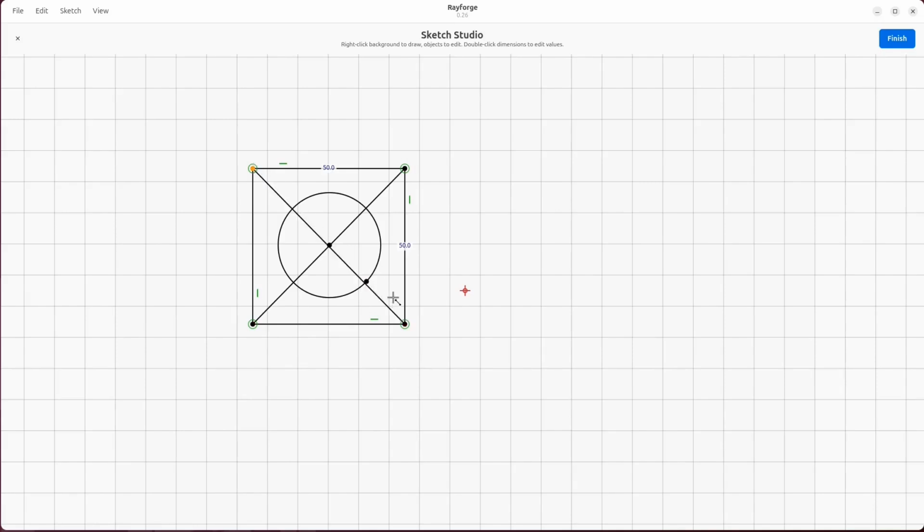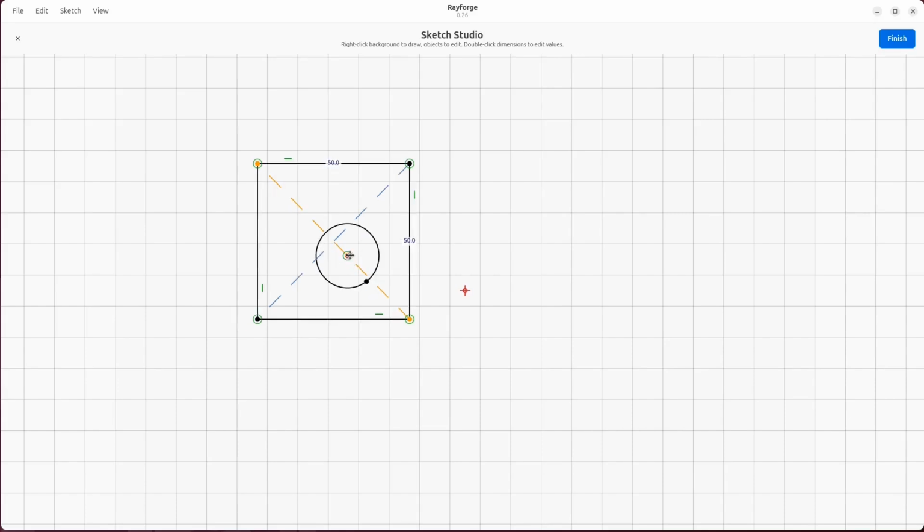And now I have two lines. But these two lines here, I want to be not real geometry that show up in the final object. They should just be helper lines. To do that, I right click here and select construction. So now they are dashed, and now I can also select the point in this, and I press C to constrain this to this line.